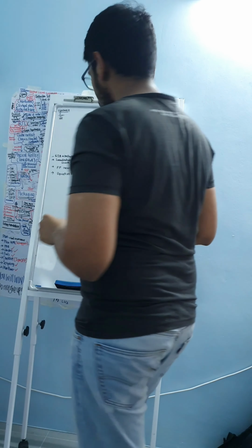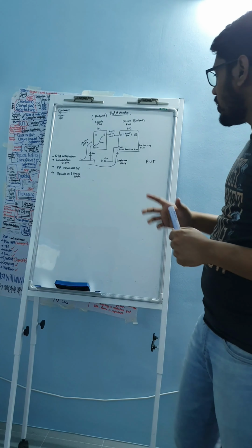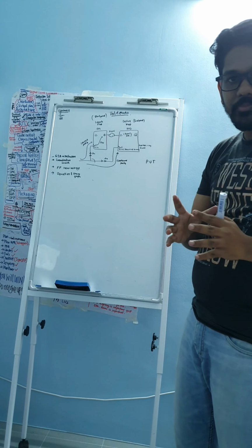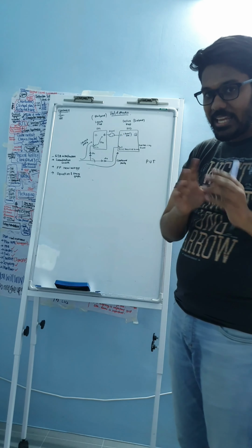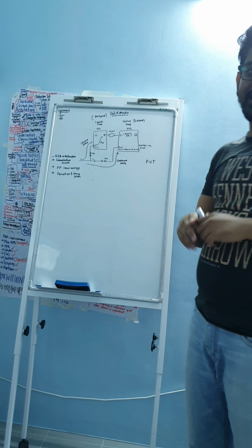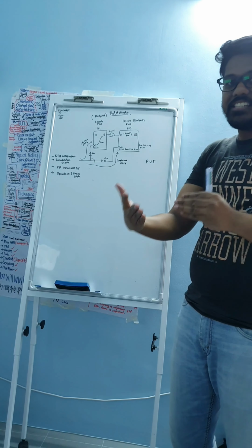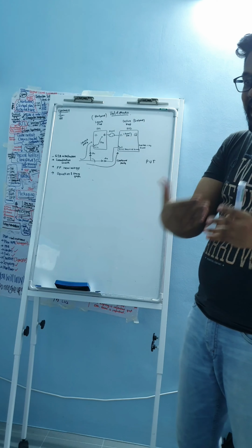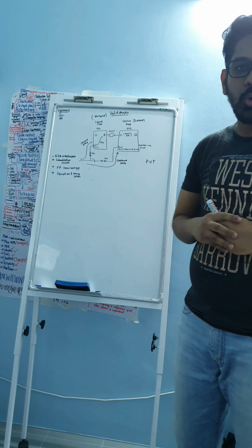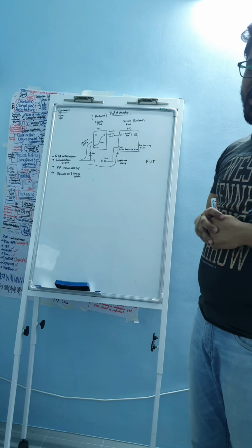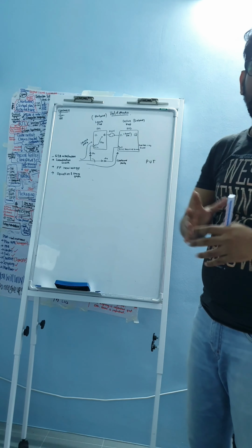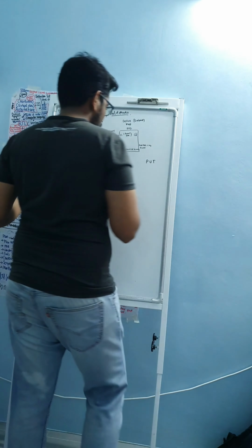In these hold checks, you have to make sure that there is a minimum amount of time the data has to be stable after the clock is triggered. If the data is not stable after that, then you're going to have a violation in the hold checks. So that is pretty dangerous. So let's put that into an equation. How do we do that?